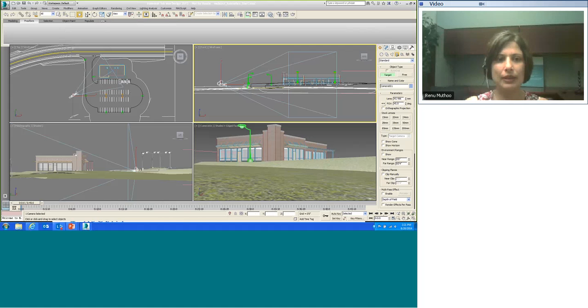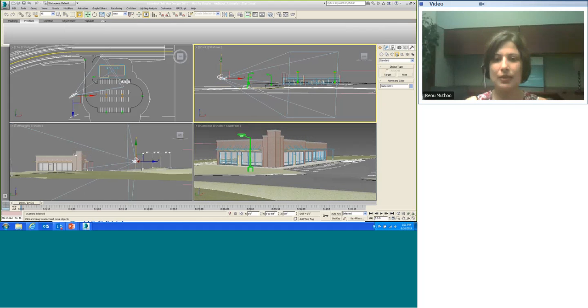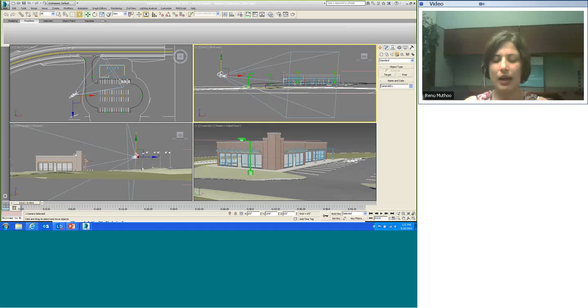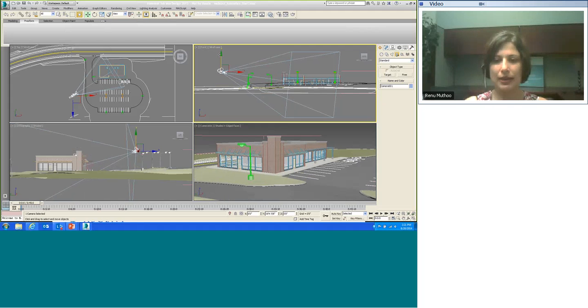So in the main toolbar, we will just say select and move this camera slightly up. And see, notice in the camera view how the field of view is changing. And I think this view looks good enough for our turntable animation. Also, we will need to move the target slightly up to make it better and get it centered somewhat.